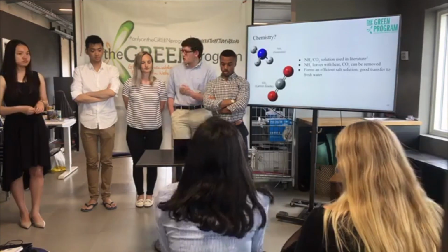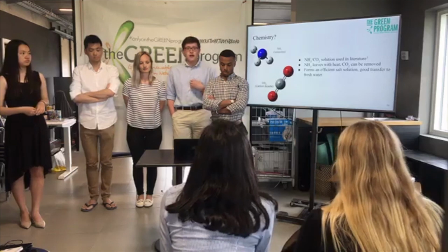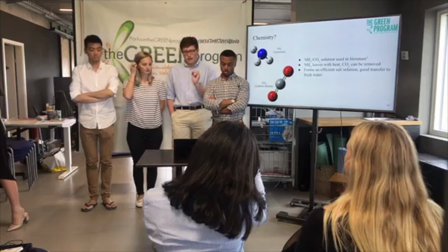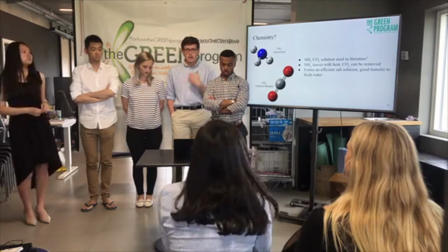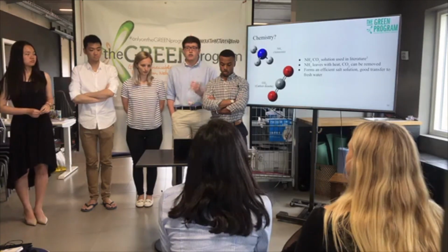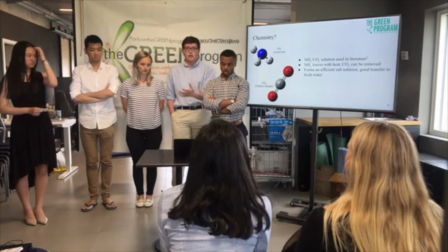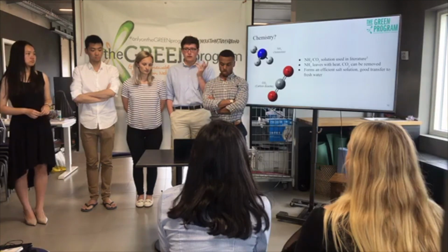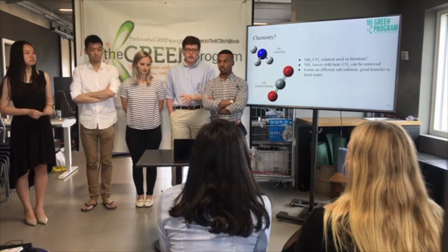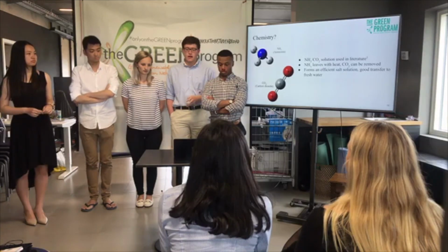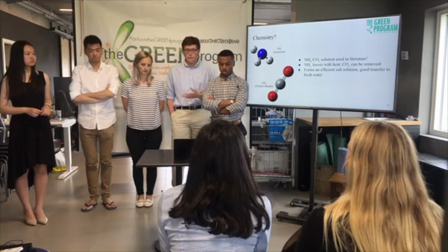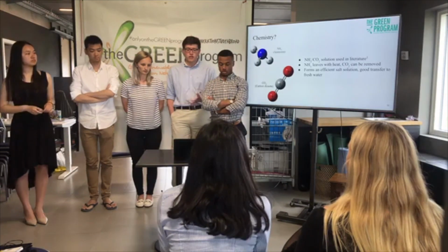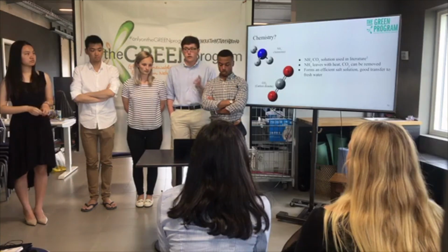The second reason, and this is what Gilbert was referencing earlier, is that as they're gases, if you heat up the solution as it's moving, you can evaporate out the ammonia and carbon dioxide, meaning there's no risk of the salt solution leaking out into the atmosphere. Instead, the ammonia and carbon dioxide will be removed, and the fresh water can safely move back into the stream. The third reason is that due to their low molecular weights, they form an extremely efficient salt solution, which means there's going to be good energy transfer to the fresh water, which makes them really useful in the cell.